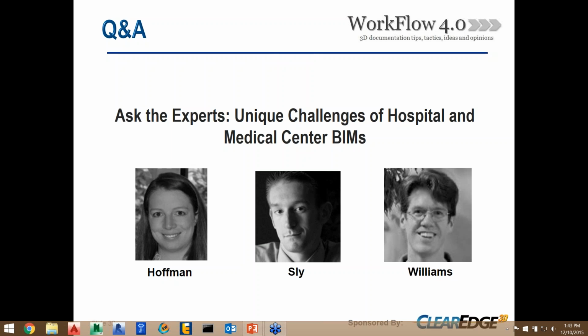So I think the scale of the project is one thing, and the other is whether there is survey set up for the project. On the 1 million square foot project we're working on, there is a surveyor out there who has control points set up, and he's worked with us. Either you can use prisms or you can have them shoot the spheres and take the coordinates while you're registering. There are different ways you can do it, but we've found a lot of use in shooting the spheres and making sure we're working with the surveyor so that the control point is set up.